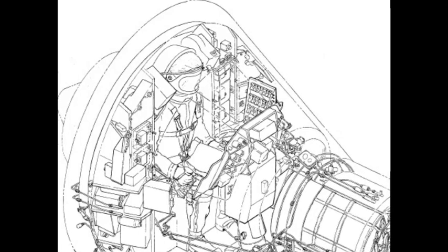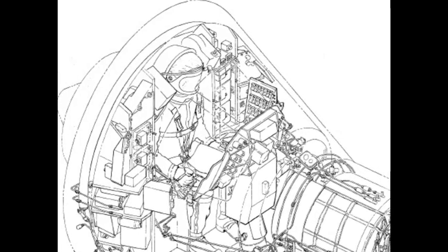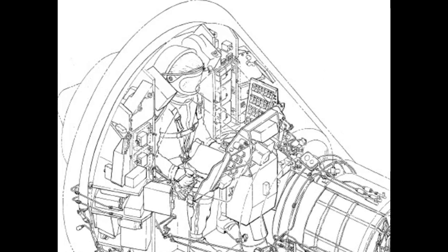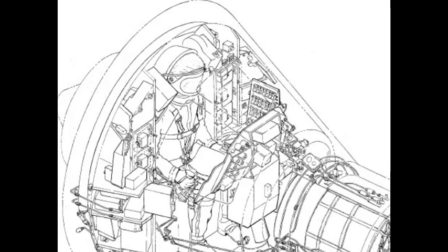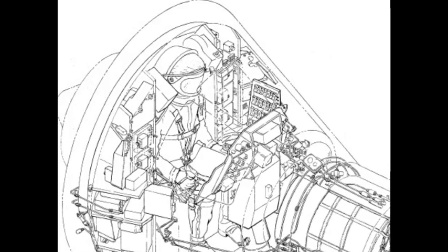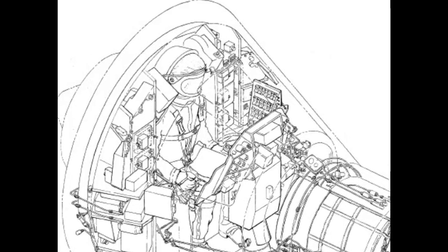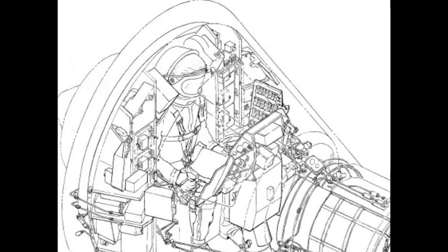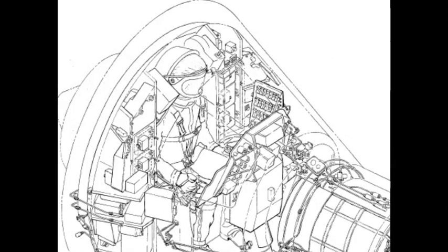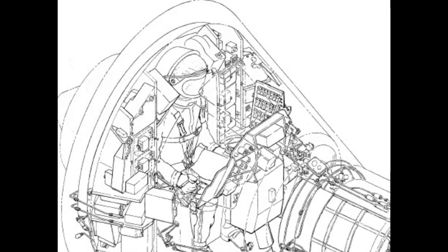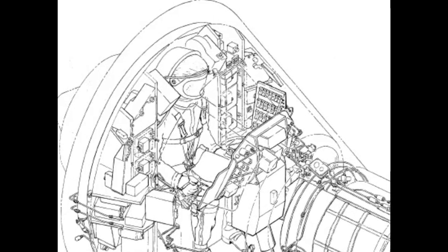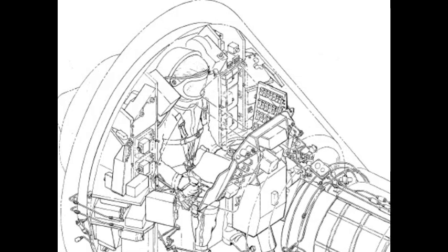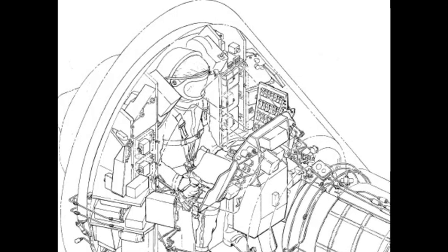223. Afterbody. Capsules 2, 3, and 4 entrance hatches, figure 2.10, can only be removed externally. Hatch removal is accomplished by removing the attach bolts that secure the hatch to the capsule. Hatch sealing is similar to the specification capsule. The entrance hatch stringers are interlocked, bolted, with the capsule stringers when the capsule is bolted in place.